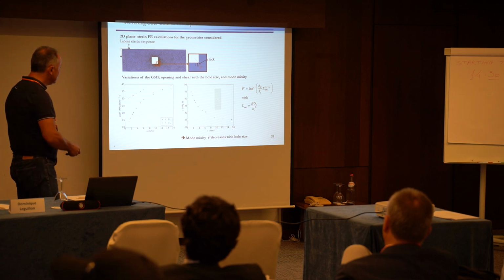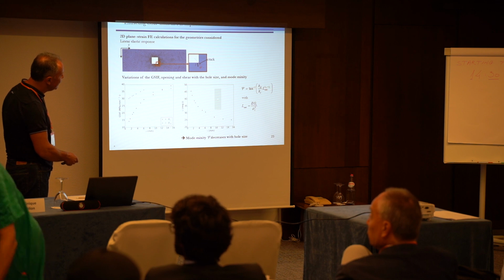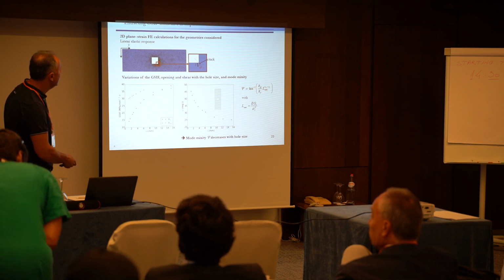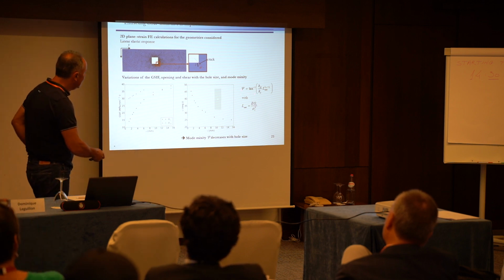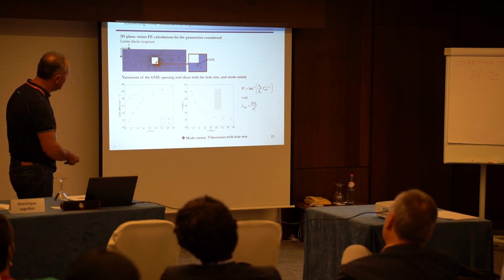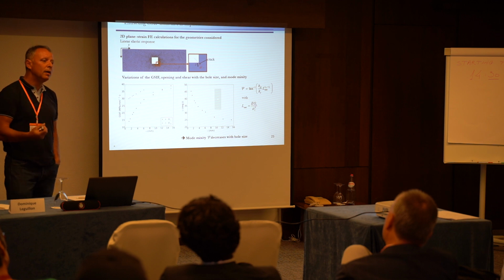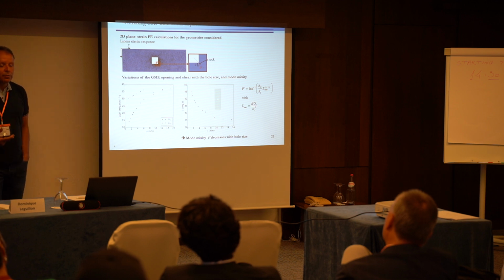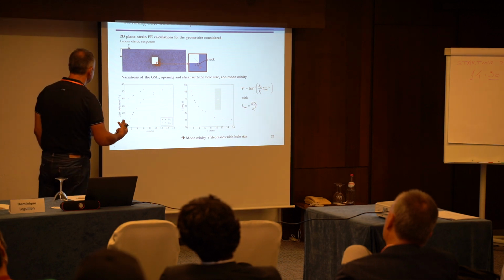What we see here is that the mode mixity, as mentioned this morning by Alberto Sapora, is also dependent on the structural parameter that is called here L max, in this case capital. It should not be C. Okay, say it is a phi, or say it is another. So it is this one. The mode mixity here goes up with a reduction of the hole size. So we come out with results that were already known analytically, but that we can recover numerically.